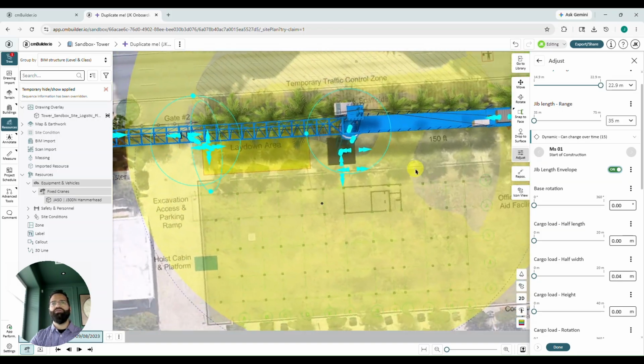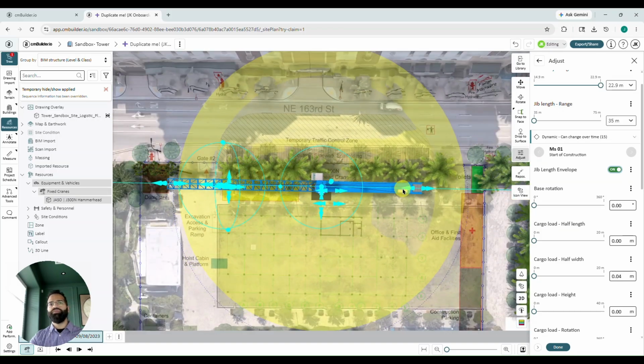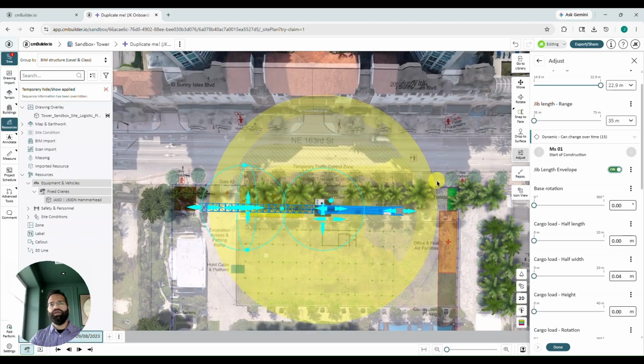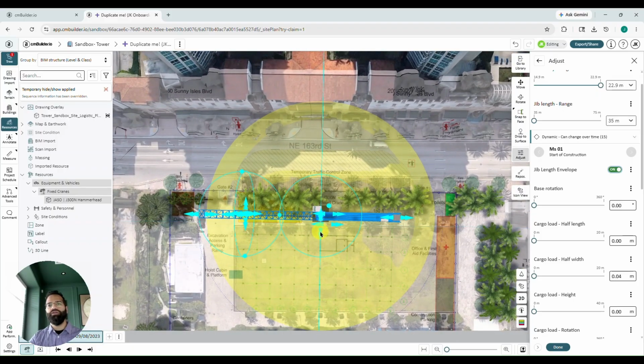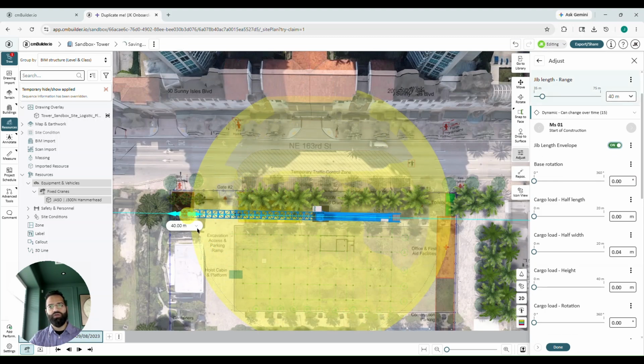And I'm going to position my view up top here. And if I zoom out and I center my view above the crane, you can see that the positioning of the crane here, it seems like we can reach all 4 corners of our building. We can see that there in the background in our drawing. But we're currently in 3D. And my recommendation whenever you are making decisions and edits from a top-down view is to click on 2D.